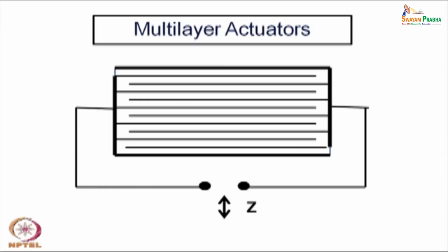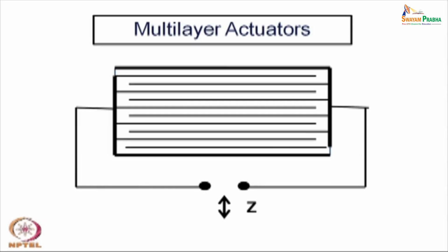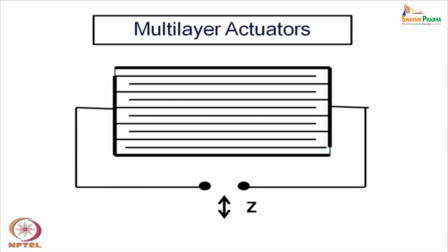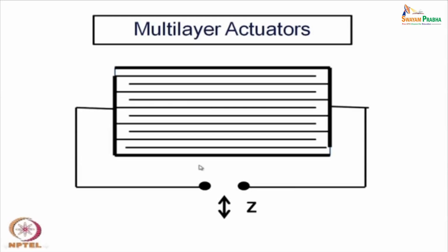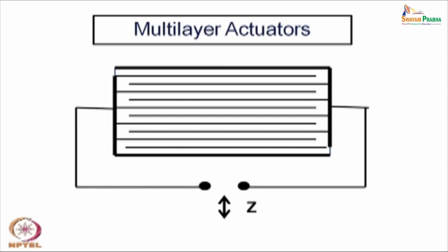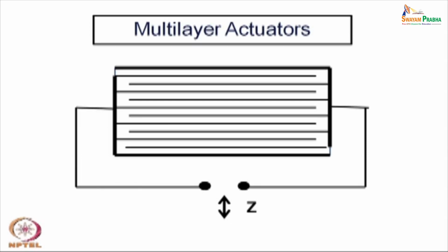So, for pressure sensors we have that is basically a sensor, whereas an actuator also makes a mechanical movement by application of an electric field. So, one can use a single layer actuator just like a single layer capacitor or a disc capacitor. Here also one can use a disc actuator, a single layer actuator or a multi-layer actuator, and the basic